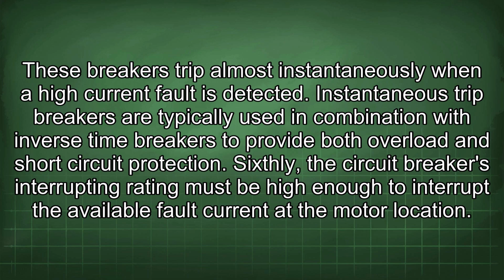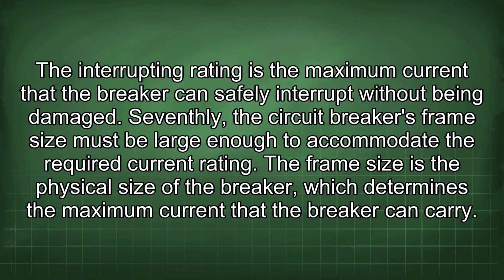Sixthly, the circuit breaker's interrupting rating must be high enough to interrupt the available fault current at the motor location. The interrupting rating is the maximum current that the breaker can safely interrupt without being damaged.